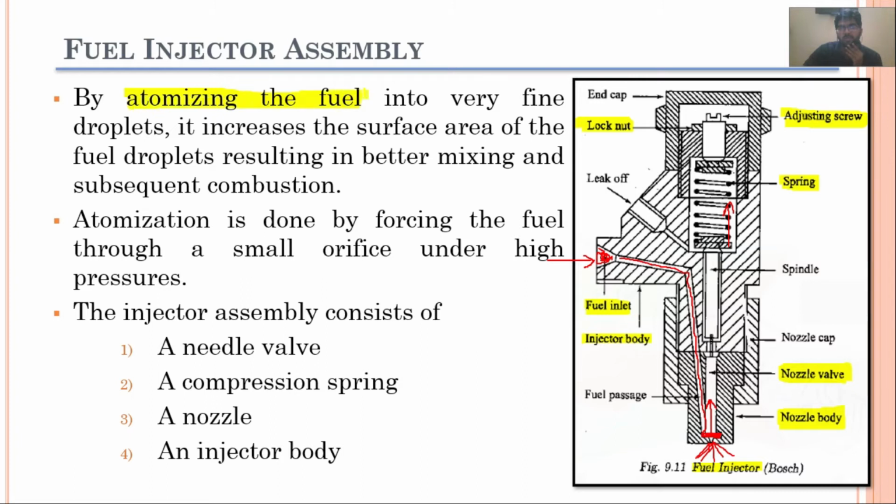The answer is that if we do not atomize the fuel, it would be injected in the form of drops, and it will not give proper combustion, and we will not have a mixture which is closer to the homogeneous mixture.